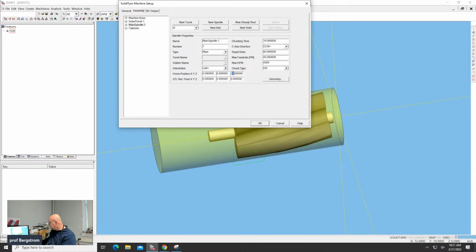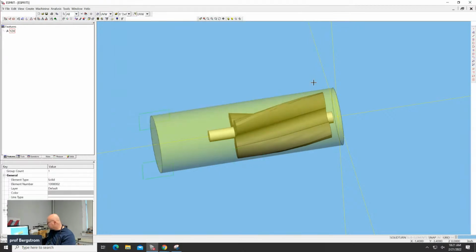Is that the front face of the chuck that it's measuring from? I don't know. Could be the front face of the chuck that it's measuring from. I've never, and so 12 was plenty. 12 makes it so that it's totally not going to crash in the simulation, like crash into the chuck, right? And that's all we really need for this phase of it. It won't impact the operation in the machine tool. It's only going to impact what we visualize in the simulation.